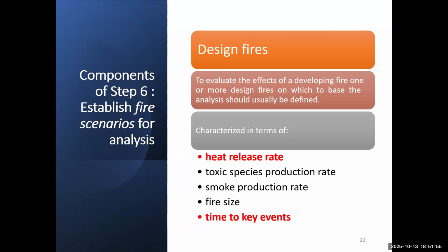Such as the flashover. Sometimes the flashover occurs in 8 minutes, and this whole, specific quantified story is our design fire. It is a benchmark we use to test if the building's smoke detectors and the sprinklers will work in time.